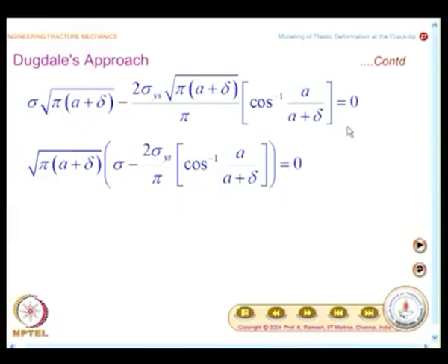But here in the development itself, we always take the complete length of the plastic zone as a correction required for the crack length. This is seen at every step of Dugdale's development. So, keep a note of this.